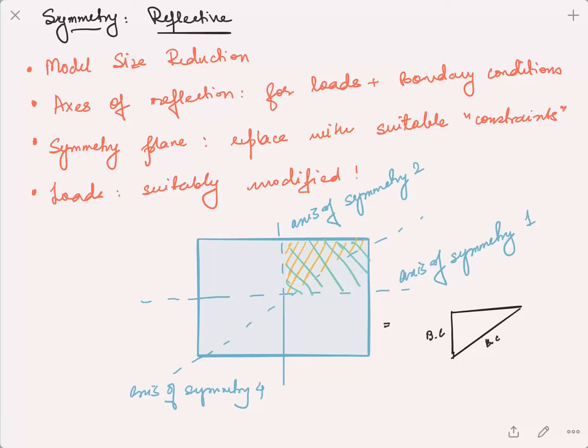Now, I remember doing this for my PhD thesis, and when I started off, there was a topology optimization done analytically with a number of equations which reduced the fuselage to just equivalent stiffnesses throughout. So that was quite simple. This was more a global analysis because I just wanted to predict what the entire fuselage in general under certain loading conditions will do and where the stiffnesses should actually lie. But once you do a preliminary analysis, you have to go into details, and that's when you need to model each and every part of the fuselage, including a bolt and a nut that would be required.